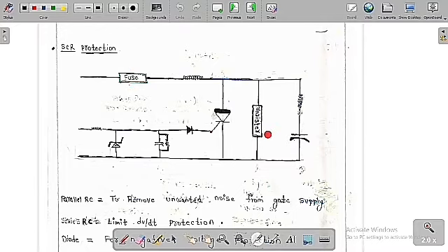Varistor: for higher voltages its resistance is low, so it protects from over voltages. We are going to make the varistor from zinc oxide. The special property of this is that at high voltages or over voltages, the resistance will be ideally zero or low, so the current is bypassed through this varistor.